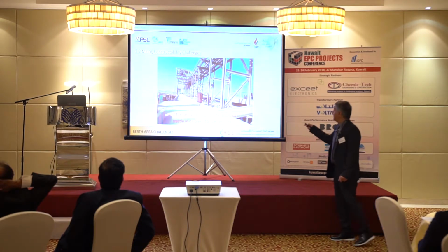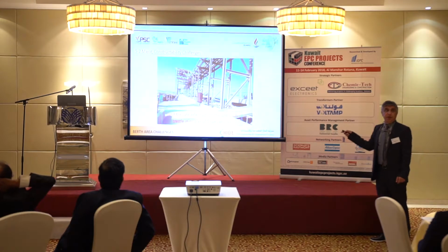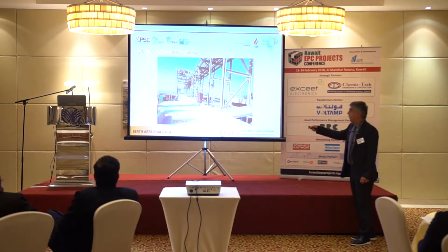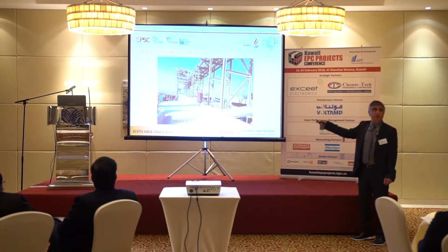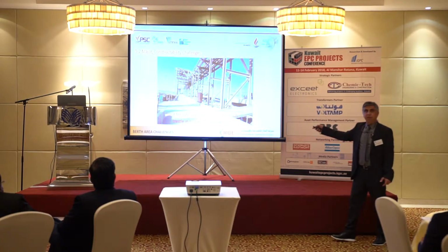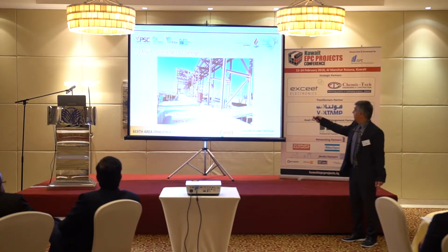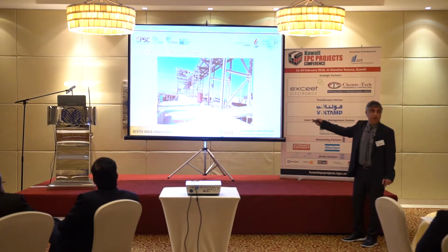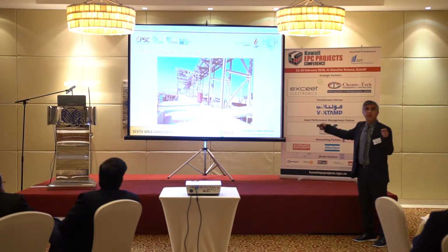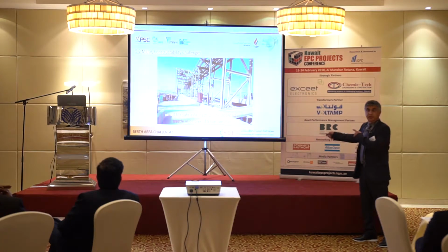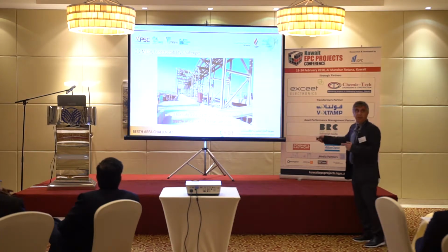Now we'll come to the major constructability challenge, and it is the high-level identified risk in this project, which is this road, which can take only a maximum load of 5 tons. If you are bringing a boom truck, for example, it's very tricky. You can only use one car to demolish 8 kilometers and reinstall pipes in this road. So considering the 6 months, it is a big challenge. This is one of the high-level identified risks, and the main core of this presentation, which you will see later.